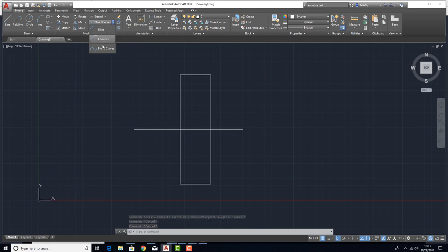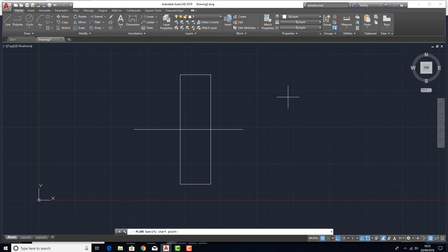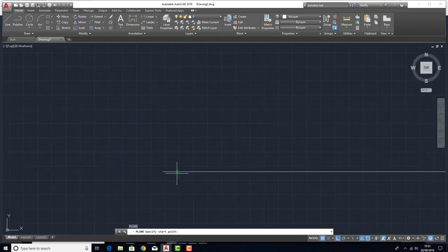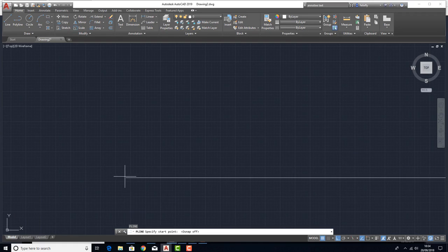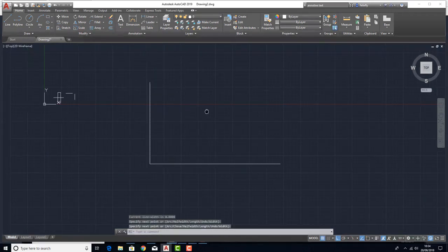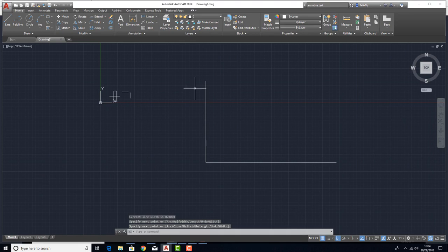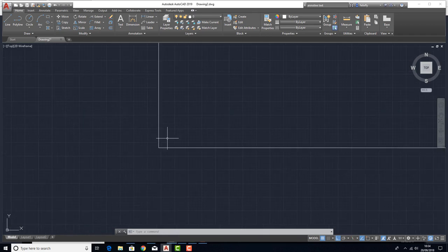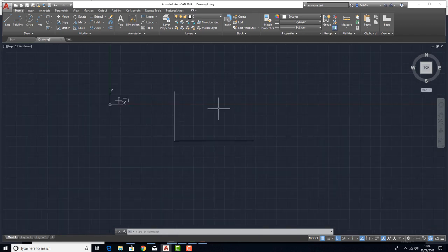let's use these fillet, chamfer and blend curves. So we have two lines like that, and you do see this a lot when you find a drawing someone else has done who doesn't really know what they're doing. They may turn off that. When you zoom out, you may see a corner like that, maybe a wall, something. It's drawn that way, but because it hasn't been drawn with any kind of O snaps or anything, when you zoom in, the ends don't actually meet. You do see this a lot, and if you try to hatch it or something, the hatch will bleed out through there, nothing will work. It can be a nightmare.